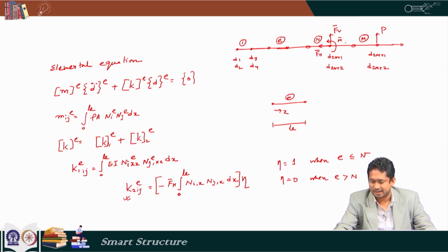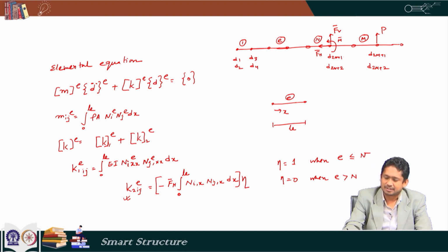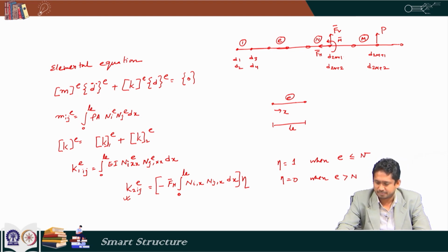So, the other components F bar and M bar and this F h, they come from the contribution due to the shape memory alloy, and the shape memory alloy wires have stresses, and those stresses are dependent on the strain in the shape memory alloy wire, and those strains depend on the displacement at this point. So, the force F bar, moment M bar and this force F h bar, they are functions of the displacement at that point itself. So, here force is dependent on the displacement.